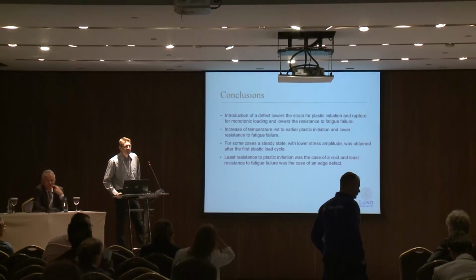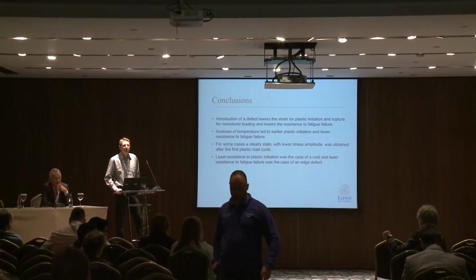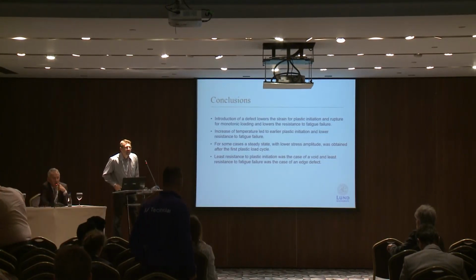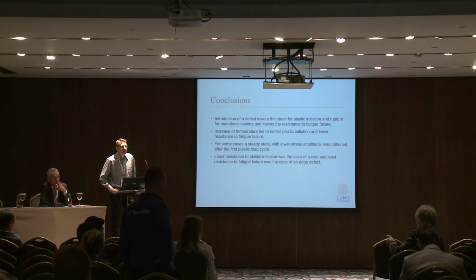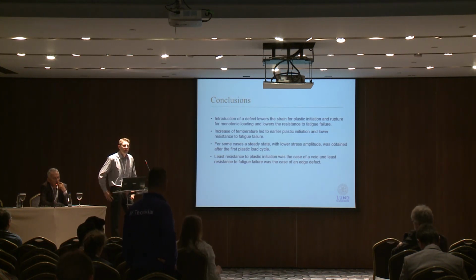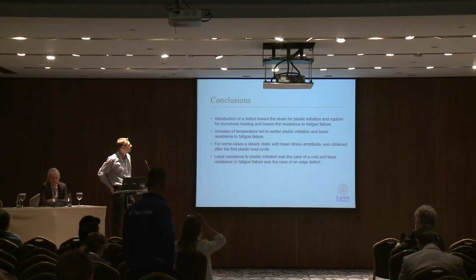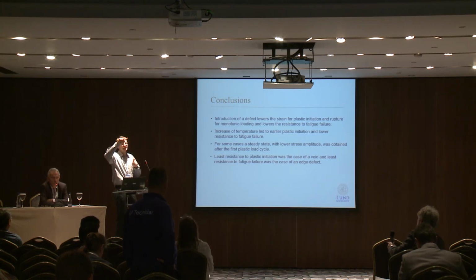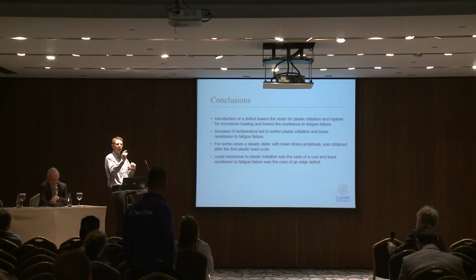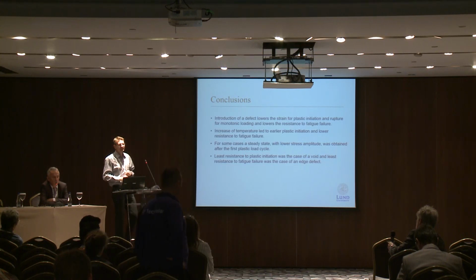If a dislocation were present in your beam from the initial state, it would behave totally different. Right? You have a perfect material without any defect in the initial state, no dislocation. No, not to start with. And I have no grain boundary, so you see these slips right away. How would the behavior change if you would insert one dislocation? Yes, probably it would go to the edge directly to form a slip step, because I have no grain boundaries, nothing to stop it from remaining in the middle. But of course it could change.